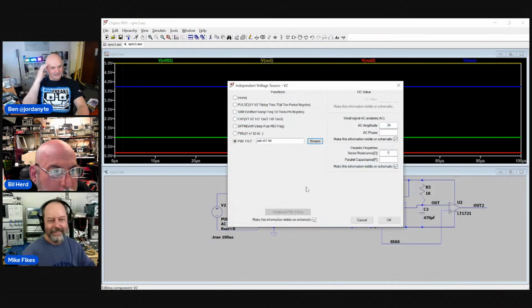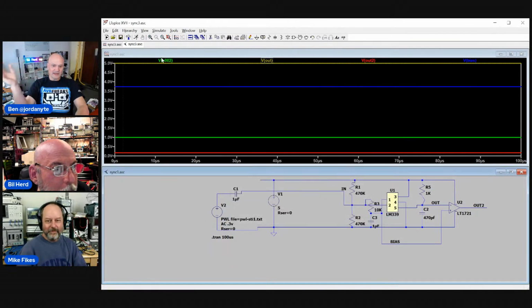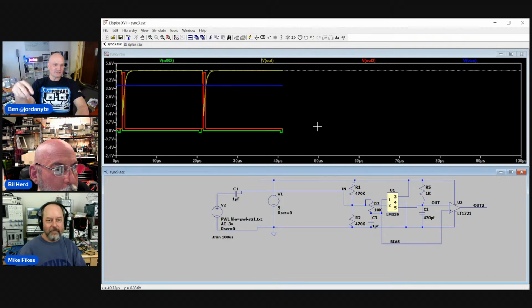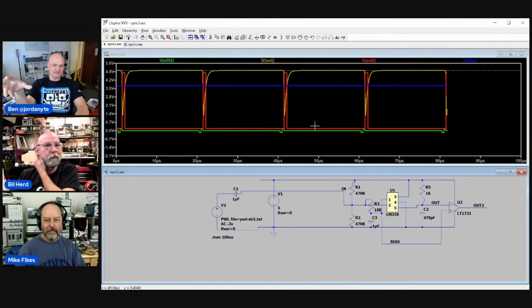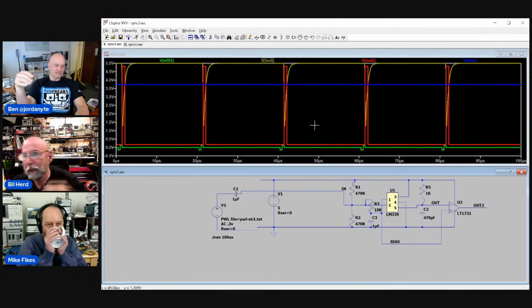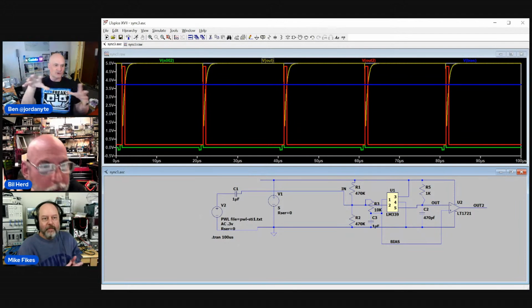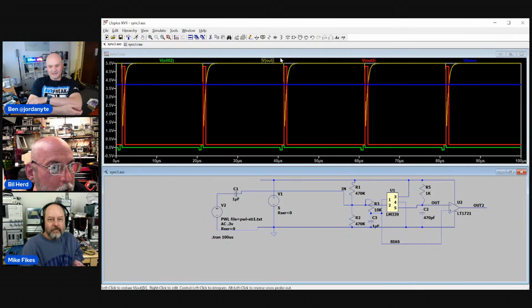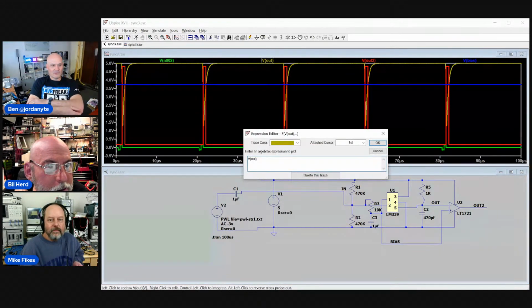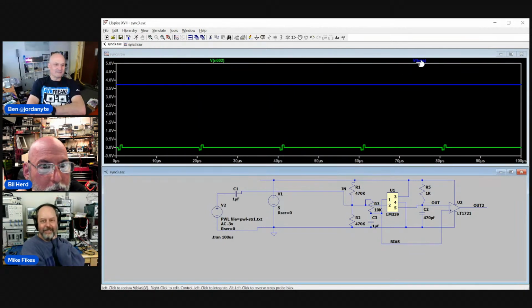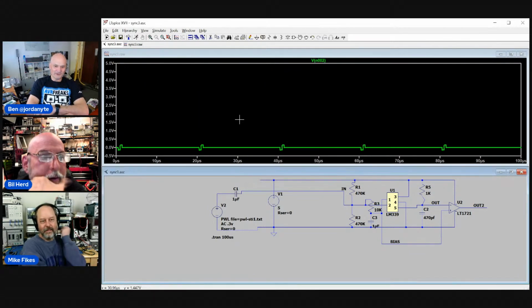This is the other thing with Spice. It's difficult, right? All the out of the box sources and Spice circuit functions. There are libraries of special functions like integrators, differentiators, multipliers, basic math functions that you want to put in, and all of them out of the box are ideal. So you have to do stuff with them to make them more like the real world, and that's where the setup gets challenging.